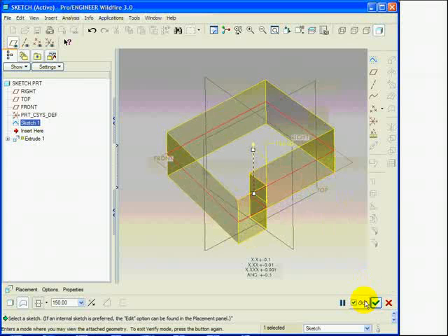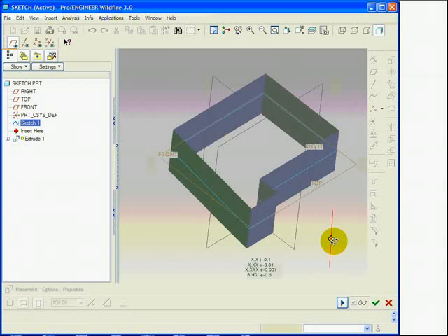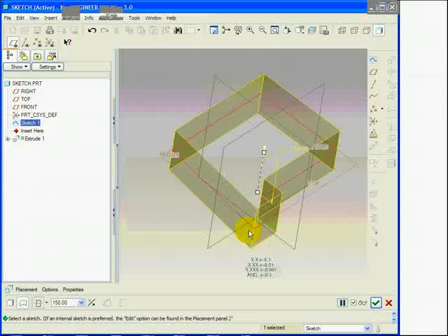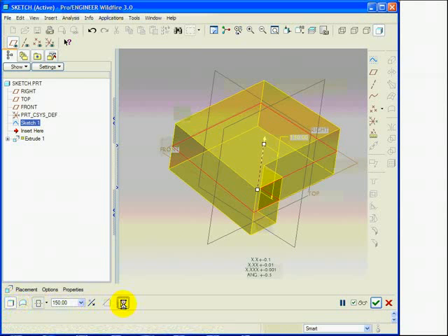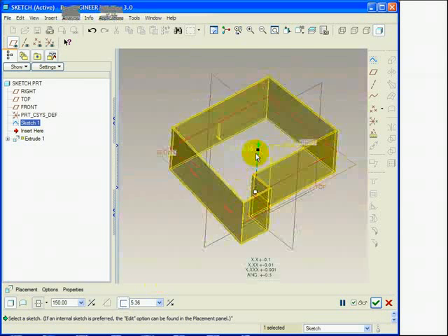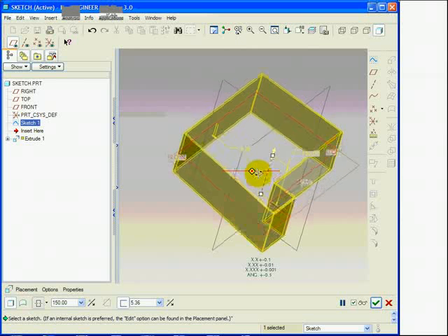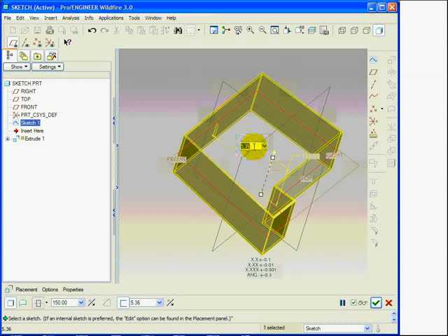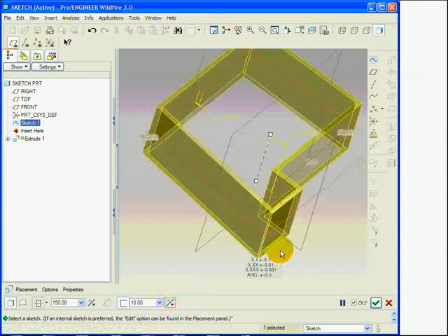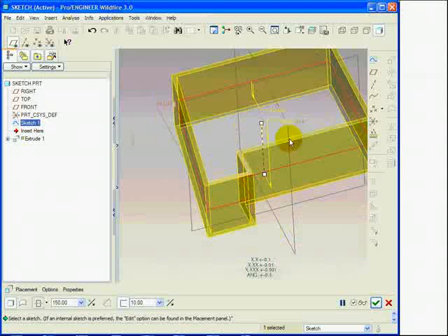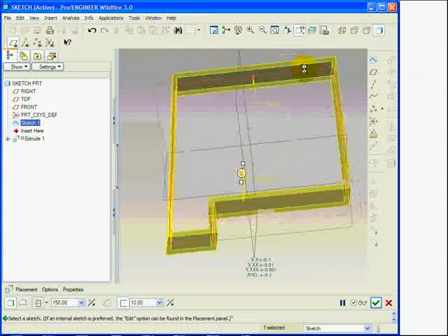I am now showing you how to turn a solid extrusion into a surface, so I can obtain a surface from a section itself. Alternatively, I can obtain a thin solid. I have to define a thickness here. Thickness is set to 10. ProEngineer inserts the material to the inside or to the outside of the section or to both sides.